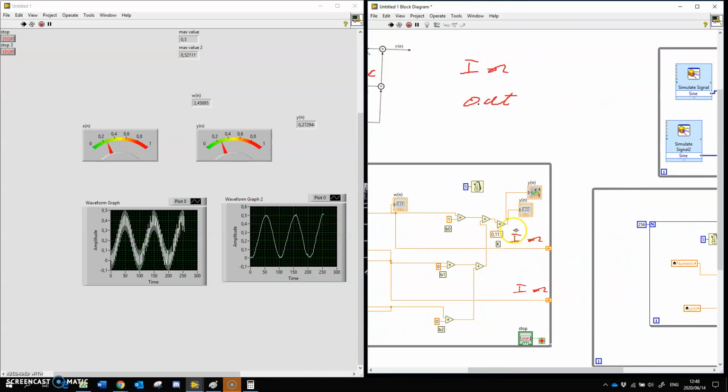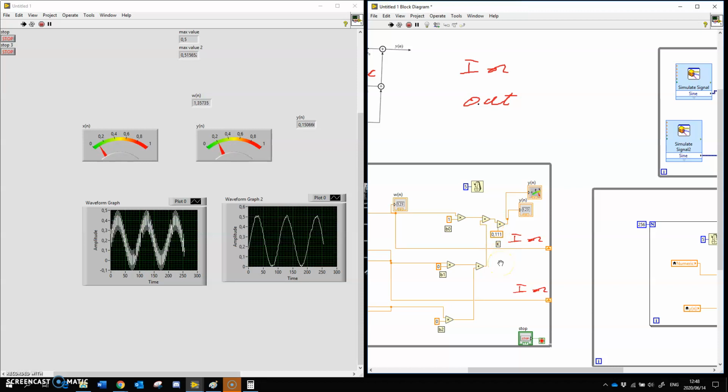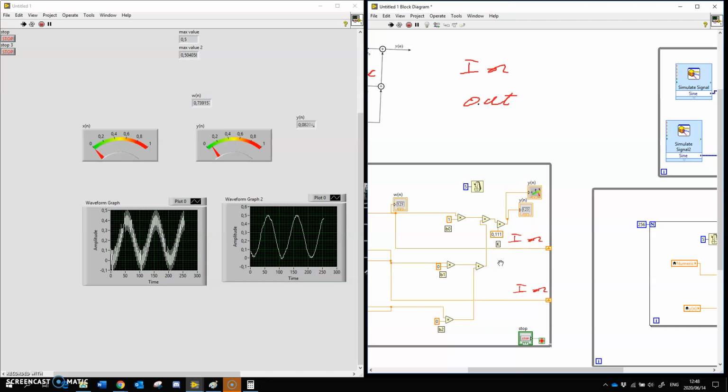Sometimes it's not a linear sensor, then you have to not multiply it with a straight value. It's going to be whatever your transfer function is. So you can see now it's this. Again, if you want this in degrees Celsius, we still have to multiply this with 100.